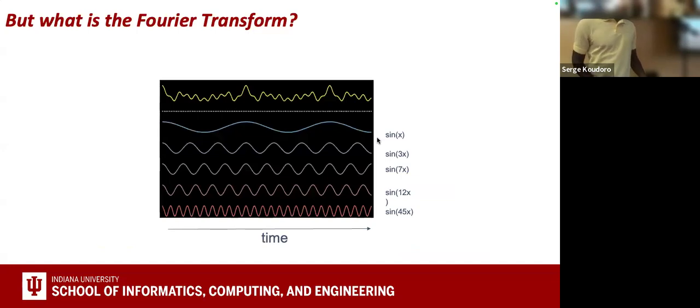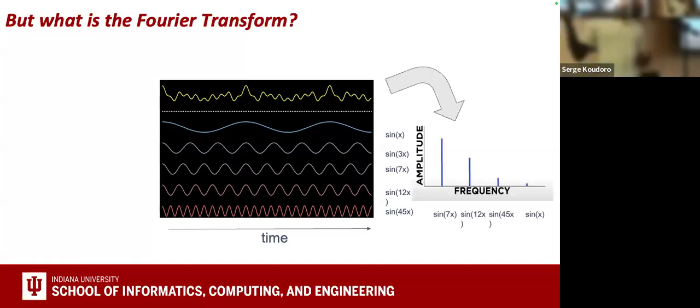So what is a Fourier transform? The Fourier transform is just a decomposition of a signal. When we decompose the signal, we change from one domain, a way to describe the signal at a specific moment, to a different domain, which is a frequency domain. If we take this example here, you have your signal on the top, you apply the FFT. You can see your signal as an orchestra, you listen to your music, and you want to decompose it. You apply the FFT on your orchestra, and after that, you know that you have a bit of the trumpet, a bit of the guitar, a bit of this quantity.